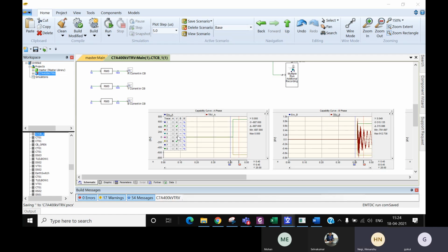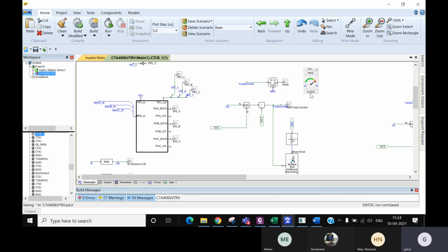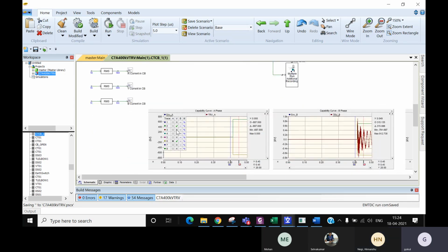For instance, I can show you that. Here we are getting 14.82, right? This is the fault current percentage. Then I have to compare with T30. I'll go into the envelope, enable these two options and check it. Okay, this 687 is T30. Then on the lower envelope also I have to check whether it's 687.